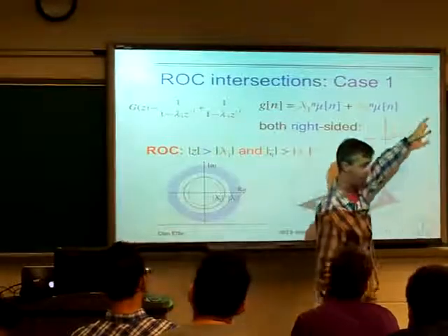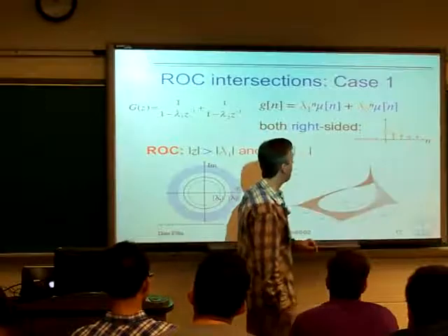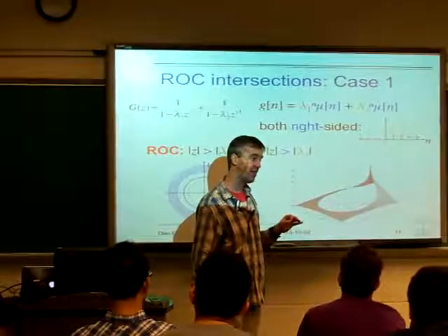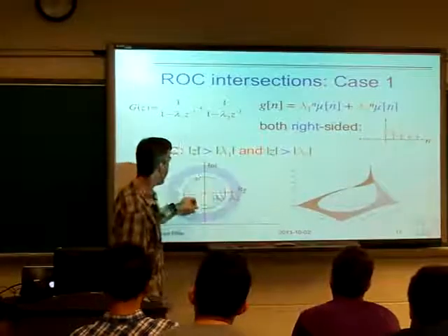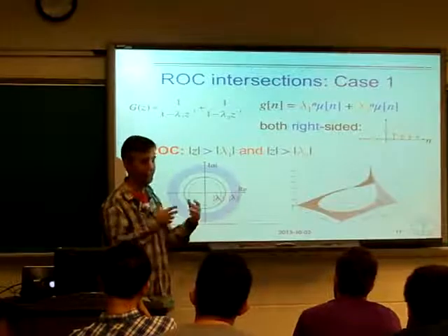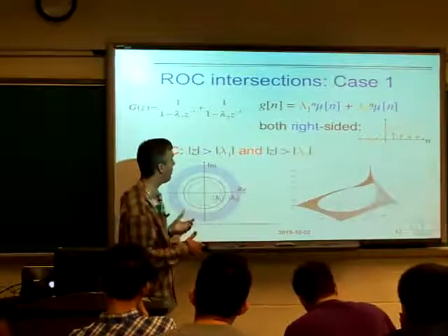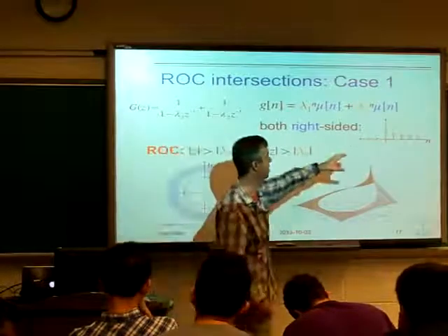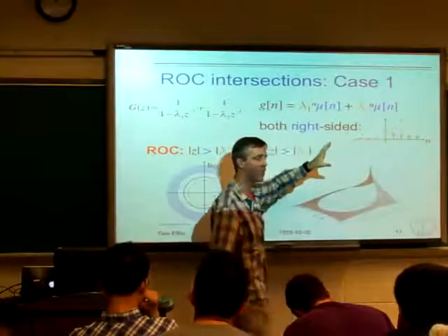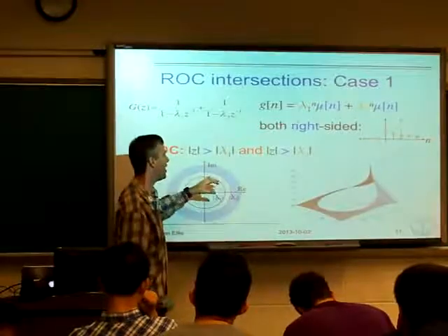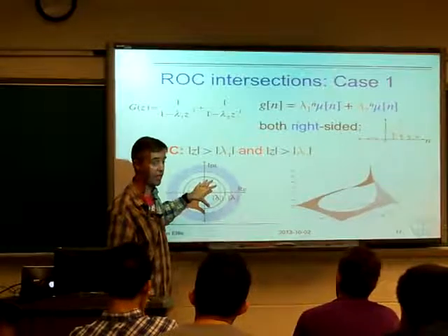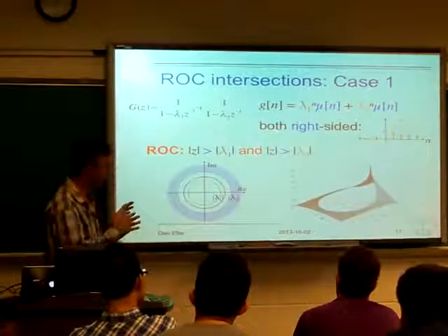The sequence is not bounded, right? The values get larger as you go on, which means that we'd have a lot of trouble taking its Fourier transform. We said the Fourier transform was evaluating G of Z on the unit circle. This solid line here, we notice that the solid line is not within the region of convergence. That is, G of e to the j omega is going to be one of these nasty divergent infinite values. And so that's sort of saying the same thing, that this kind of sequence is not something we like to deal with in discrete time because it's not bounded. The Fourier transform method is not going to work for us. That's the same as saying, yeah, you have a closed form expression for G of Z, but it's not valid on the G of e to the j omega values that you care about. So that's sort of how that all plays out.